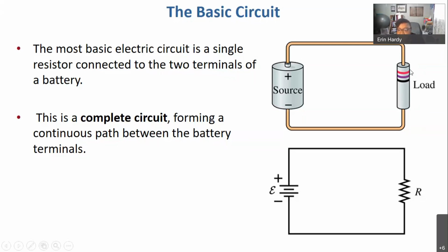But if you're new to it, this red, purple, black combination would be my clue that that resistor is different than if I found a green, red, blue, or something like that. So at a glance, you can tell what resistance is without having to put that resistor into a circuit. I can take this kind of cartoon circuit and turn it into my simplified circuit diagram here.